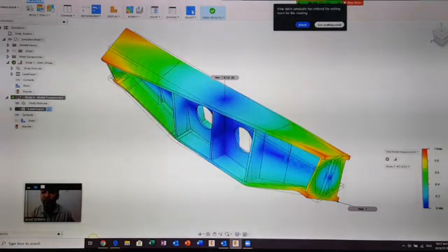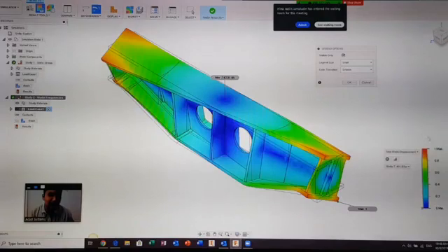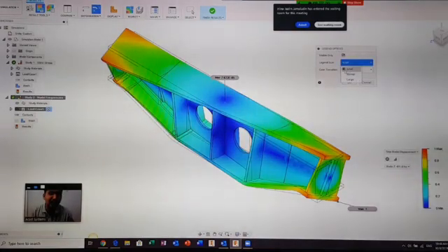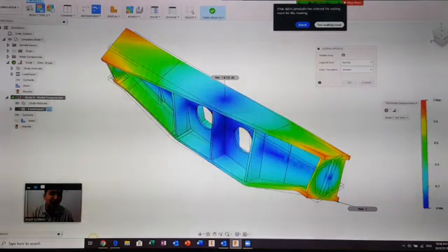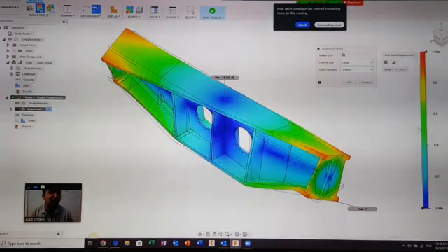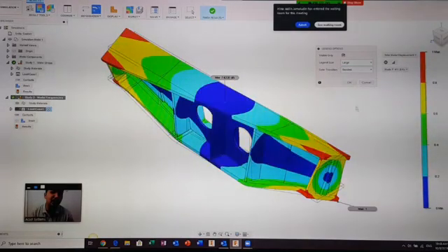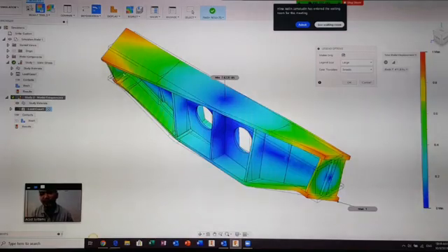So under the result tools here, the legend option is these things. The probe here is the legend. Let's say the size, now the size is small. If you want to make it bigger, you can check the normal one. Now it becomes bigger and larger. So this one is the biggest one. For the color transition, you can have smooth or banded. Banded will make a little bit more drastic color. If you pick the smooth one, it will blend your colors inside.